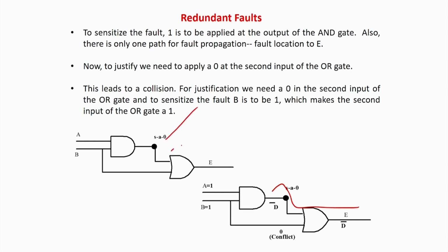But if there would have been many fan outs, then it would have been a real soup, because you have to try so many paths. Maybe I am assuming that there was no other path from which the fault could be successfully propagated and justified, and having that assumption, only after a huge number of iterations would you have been able to conclude that. Not a good way of handling.